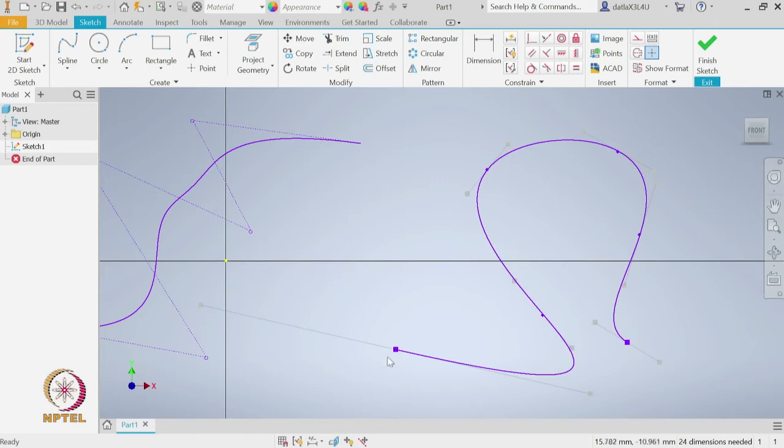So, now we can see the curve which is coming up, the spline curve which we now created is passing through all of these control points. So, these are the two kinds of splines we can create and later we will use these splines to create solids, but let us now move back and look at the second command.